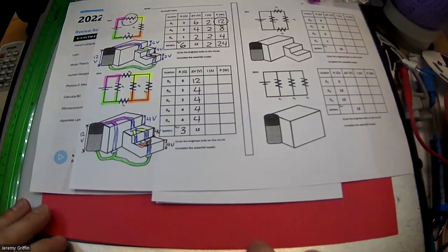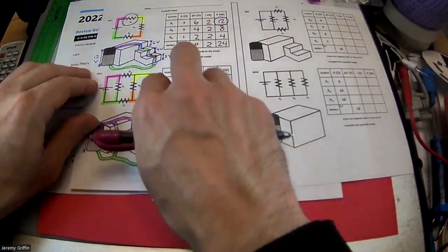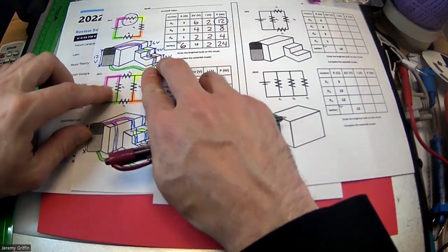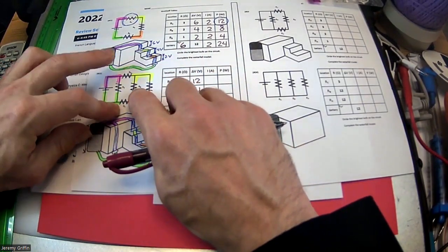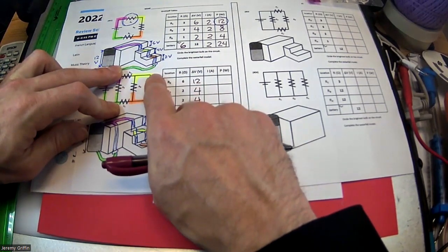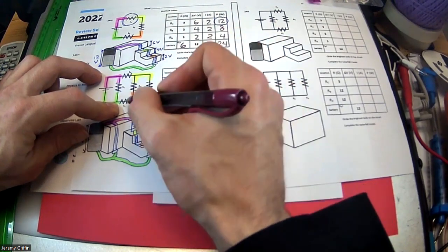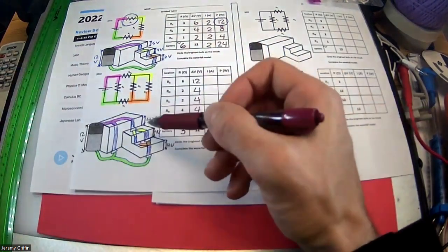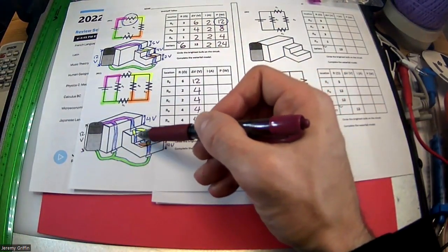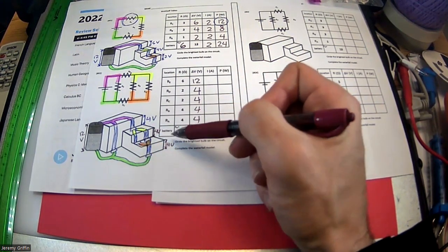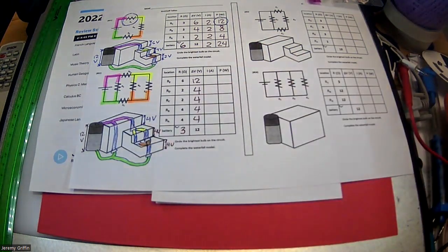So you're saying A, B, and C have to add up? Well, how about C, D, or hold on. You could do C plus B plus D have to add up to 12, like the battery. Or if you go around the outside, this one plus this one plus this one. But just don't double count resistor A and resistor B because they're side by side. These three heights have to add up to the full battery height. 12. Any questions so far?